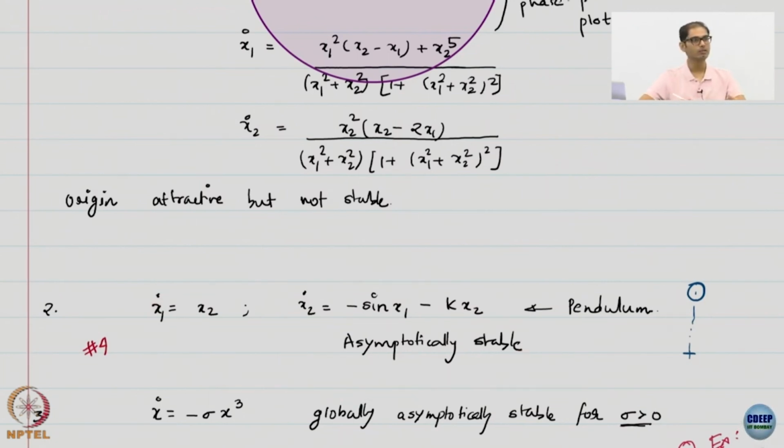It is difficult to solve this system, just because of this sinusoid you will not be able to analytically solve it, but you can just look at the movement of a pendulum, you know that it is attractive, because of this damping term. This damping will come usually from the friction in the pivot point. So, if you make any pendulum move, it is going to stop at the bottom.